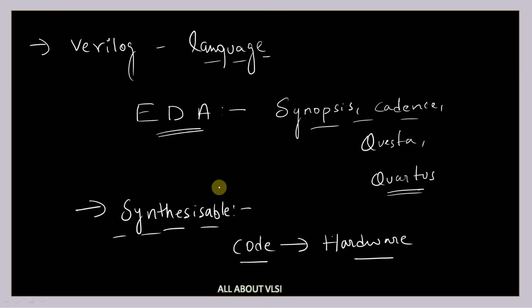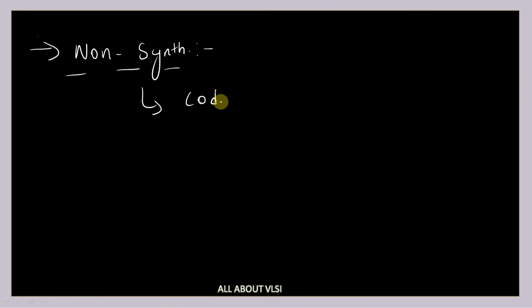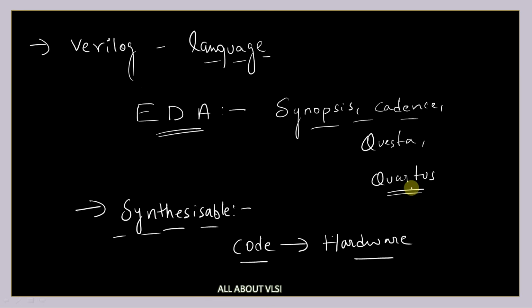And Verilog also supports non-synthesizable constructs. What do you mean by non-synthesizable constructs? If you use these particular constructs, your code will not be converted into hardware. So Verilog has both synthesizable constructs as well as non-synthesizable constructs.